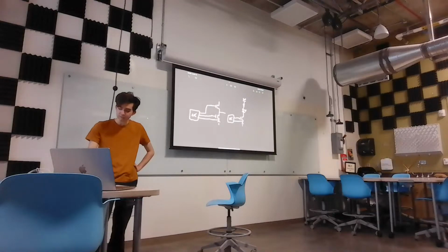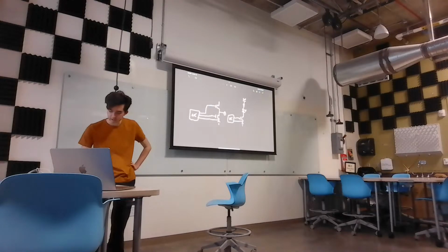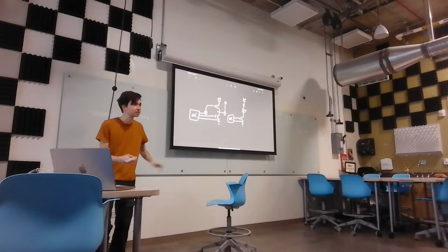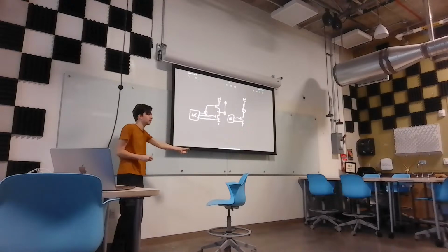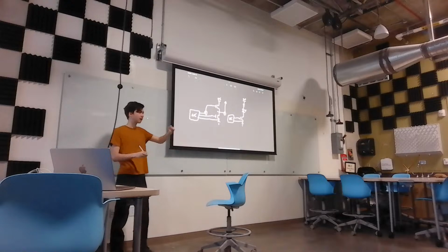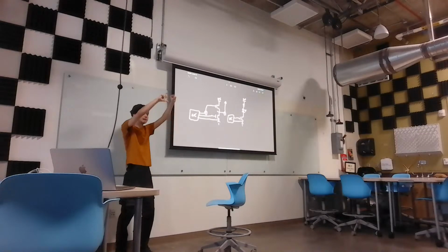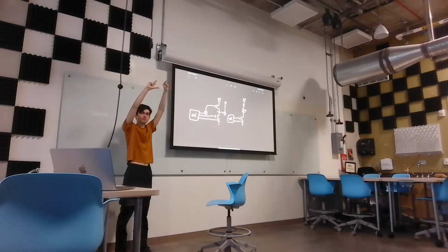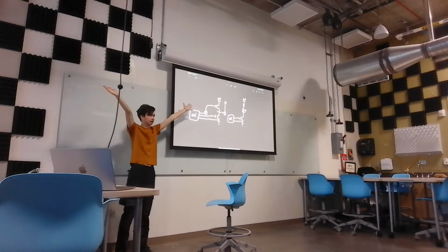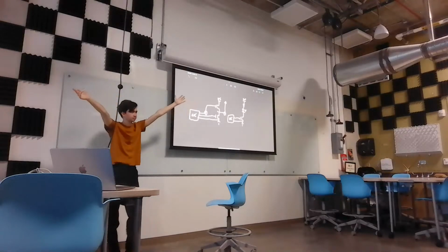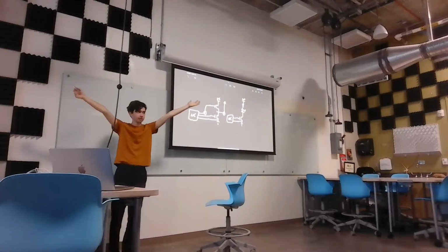Because when this MOSFET turns on, this voltage goes up. It goes up to around here, I'll just call this AS. That means that this is way bigger than this, which means that the gate-to-source voltage is now smaller or severely negative. We need somehow that microcontroller signal to lift up with that high side FET as it turns on. Does that make sense to everyone? Is there any confusion on that? Good, that's good. Yes, George?